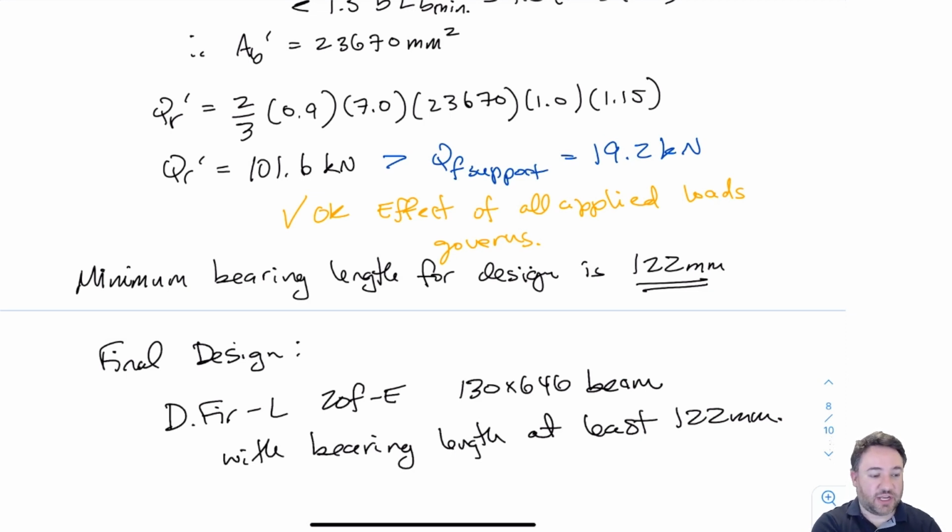We looked at our shear strength. We looked at how to increase our shear strength a little bit by using alternate methods to look at either Vf at d or using the detailed method for shear. And then we looked at calculating what our minimum bearing length is. And after all of that, we've come out with a beam design that is adequate for what we were looking for.